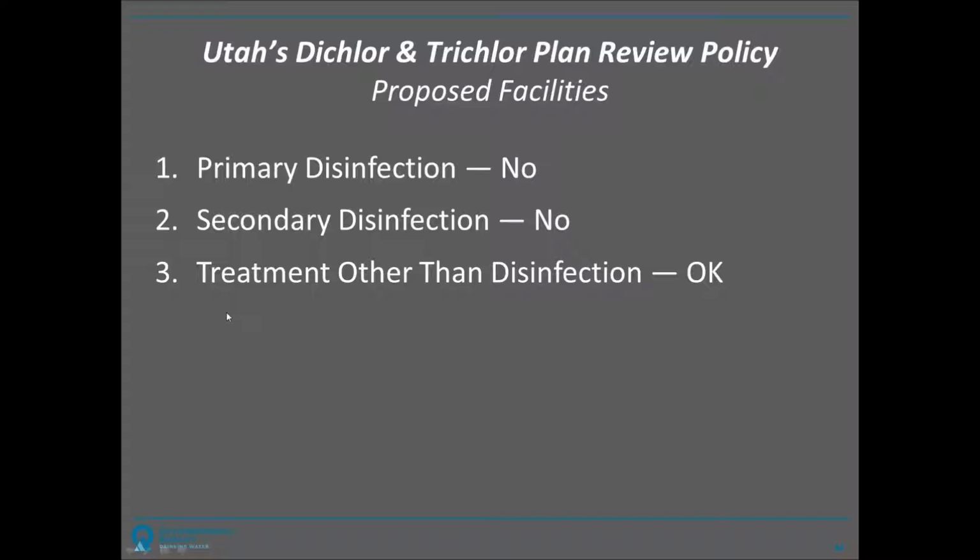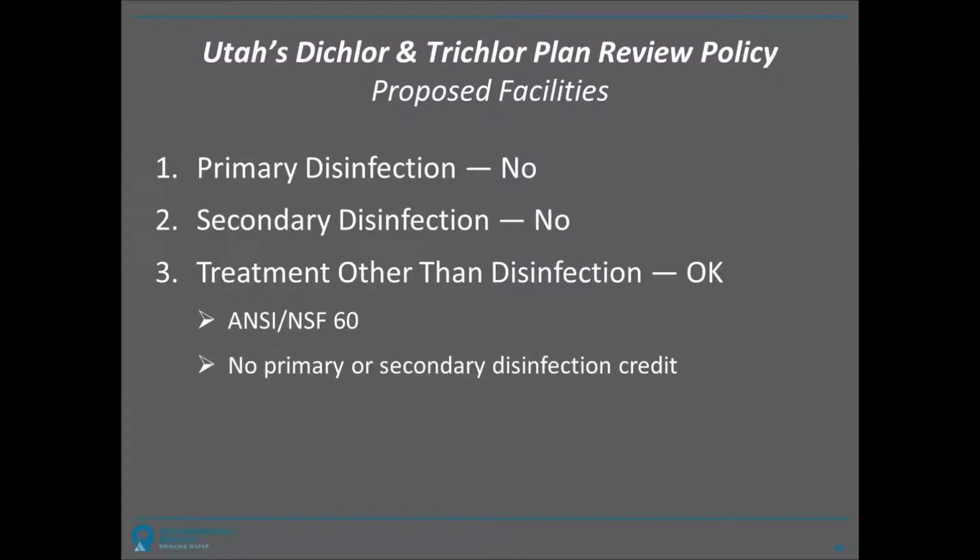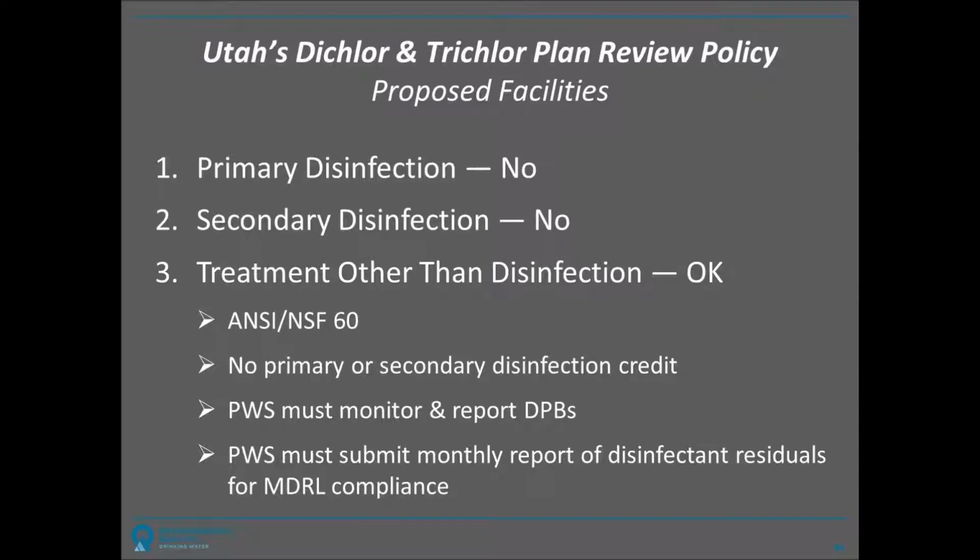But if a water system proposes to use dichlor or trichlor for another purpose, that would be just fine, because many of the dichlor and trichlor chemicals have received NSF 60 certification. That means it's okay to use for drinking water treatment. However, we will not give primary or secondary disinfection credit to these installations.